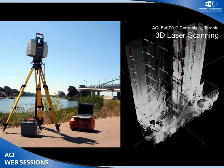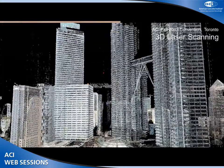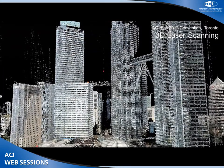Compared to the measurement using sensors, the overall movements of a building can be easily captured by surveying the as-built condition. Although visual inspection is the usual way of surveying, it heavily depends on the naked eyes. So we have adopted the 3D laser scanning technology to survey the verticality of the elevator shaft, as shown inside out on the right. As a research purpose, 3D laser scanning technology was also applied to a survey of tall building. It is known to be the first trial in the world.